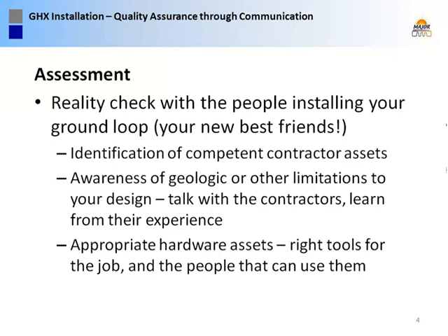The other thing is understanding what contractors have, what kind of assets. If they don't have a big enough drill rig for deeper work, or they can't do shallow surface casing, that needs to come into your evaluation thought process as you go through your design.